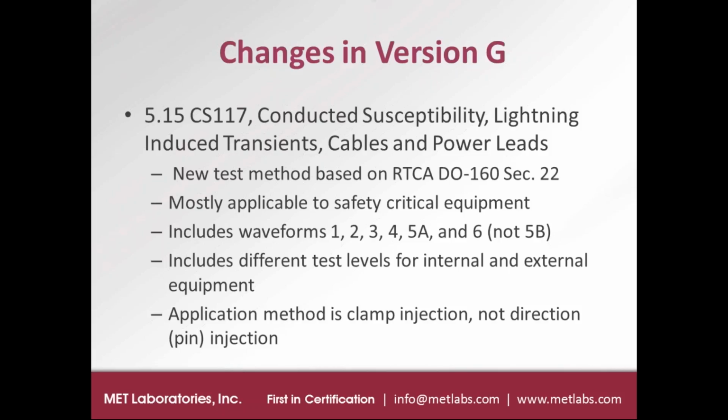Within MIL-STD-461G, the applicability is explained, and you could summarize it as mostly applying to safety critical equipment, and equipment and cables that are connected to safety critical equipment. There are some other pieces of equipment that are listed as applicable as well. This test method includes waveforms 1, 2, 3, 4, 5A, and then waveform 6 from RTCA DO-160. There is also a waveform 5B defined in RTCA DO-160, and that one's not carried over at all into 461G.